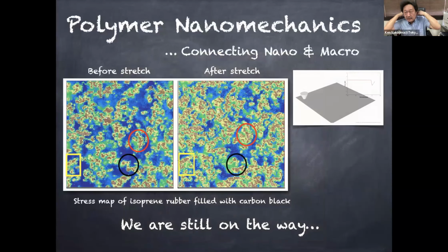And once again, coming back to my research, as I mentioned, I use atomic force microscope and not just looking at the structure, but in this case, I push the very sharp AFM probe to this material one by one, next by next. And because you are pushing with a very sharp needle, you can have nanometer scale resolution modulus mapping like this cartoon movie, and finally get this type of experimental result.